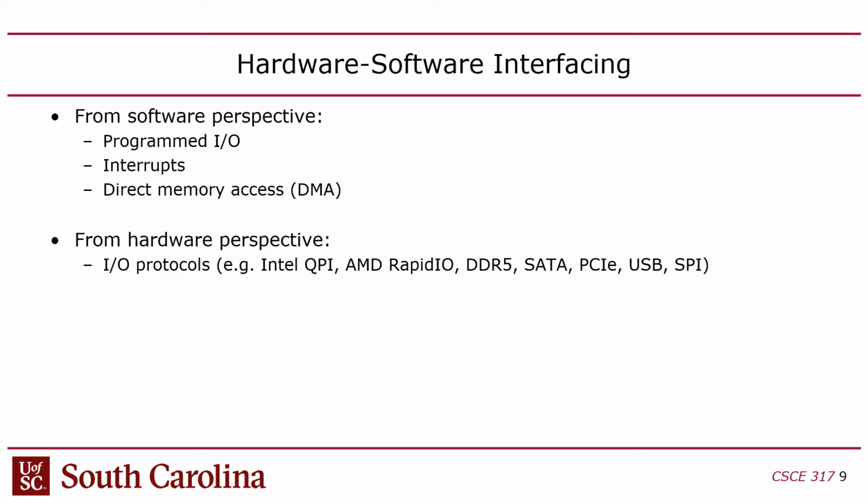It's a wire that goes back to the CPU. It's a signal, usually basically you think of it as a single bit. Sometimes it's more than one bit, but it's essentially a signal that's sent back to the CPU from the peripheral. It causes the CPU to automatically go into the driver, at which point it starts doing programmed I/O to figure out what's going on and how to service that interrupt, okay?